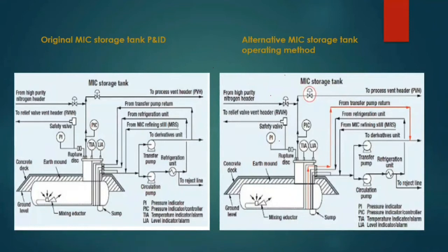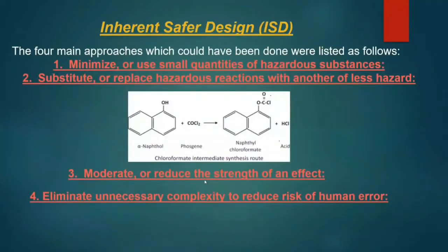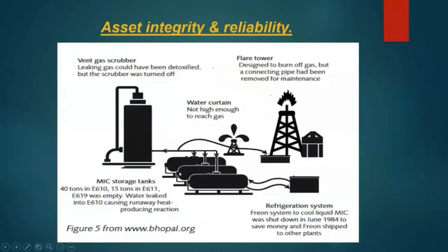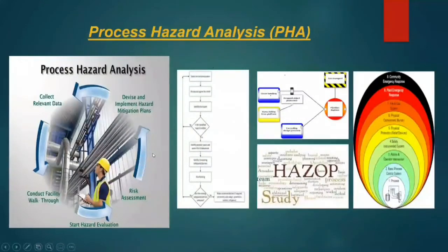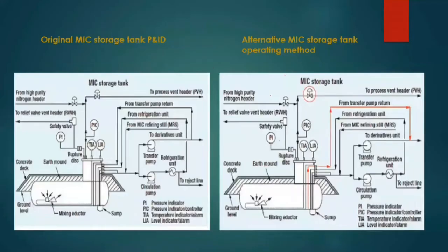If you remember the figure before, there are three tanks. 610 and 611 are storage tanks, and 619 is the emergency or evacuation tank. Again, back to the P&ID. An identical tank 619 received contaminated material from either tank 610 or 611 on an emergency basis only. This tank provides extra storage volume to allow for an adequate response to potential thermal runaway.